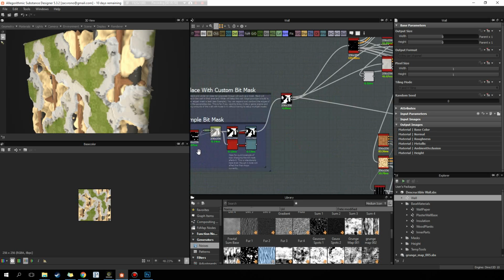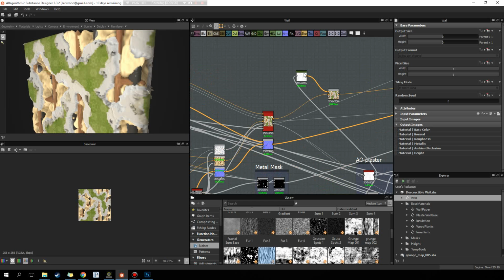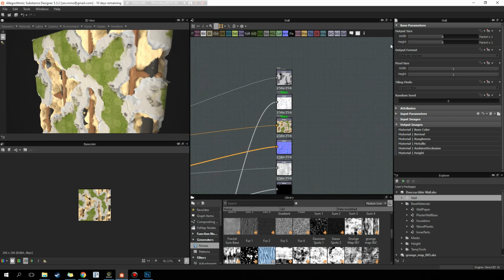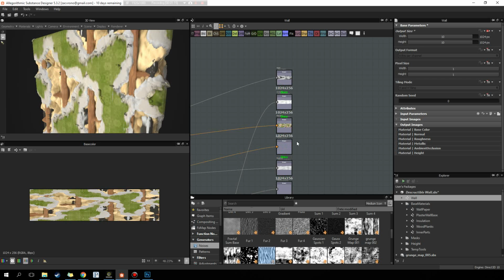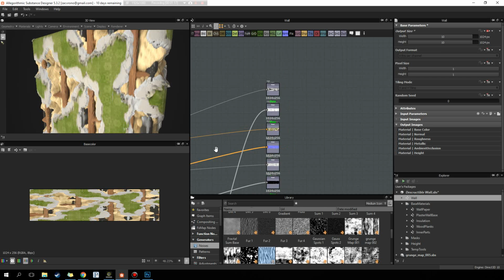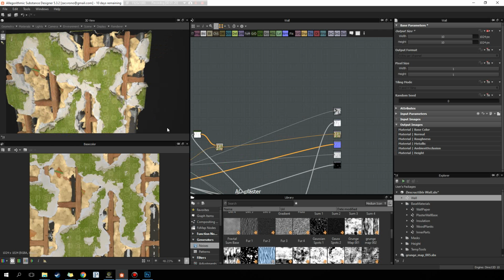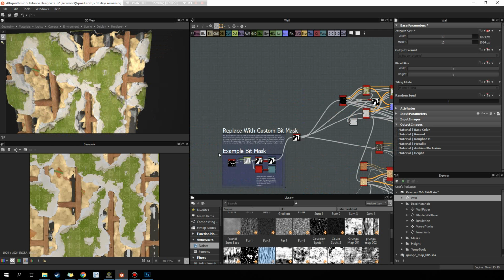Essentially how this works, let me go up to full resolution. When you download it, it's only going to be rendering in 256 textures. So if you go over to base parameters, absolute, you can change that by increasing the numbers. I'm just going to set it to 1024 right now. It can go to 2048, 4096, etc., whatever your computer can handle. I'm just going to keep it at 1024 to be fast for recalculating while I record.